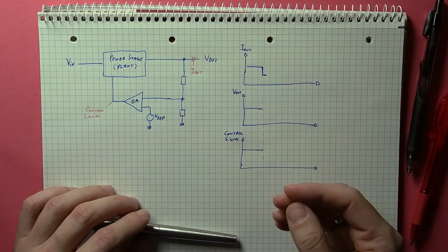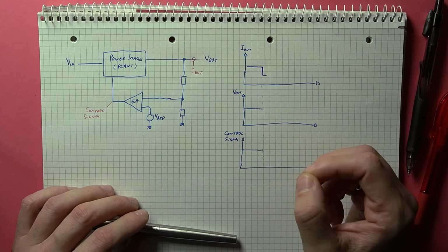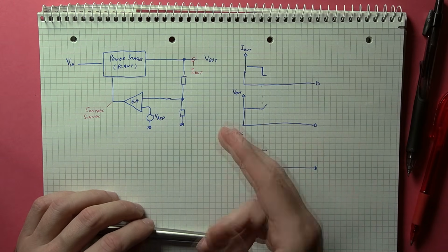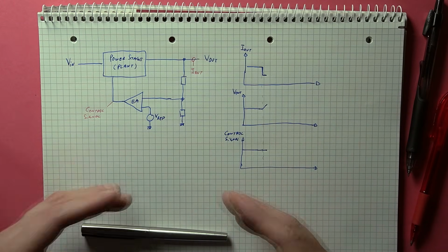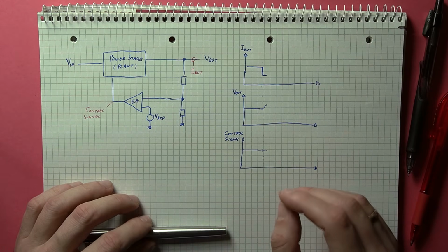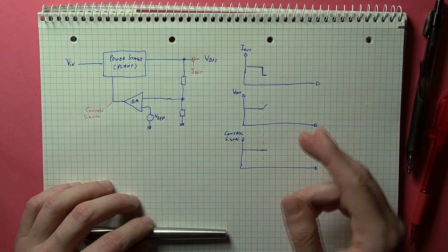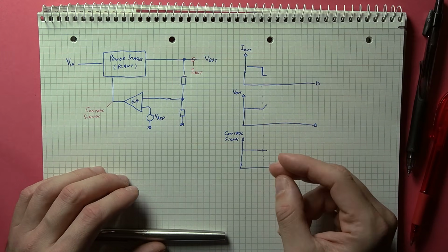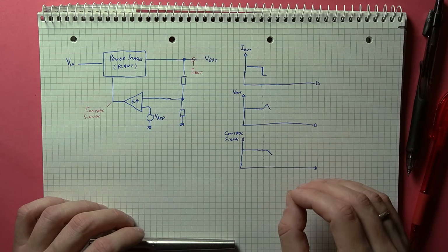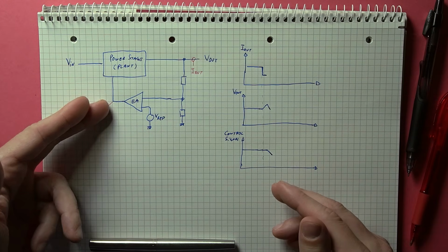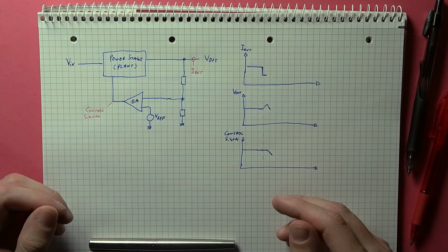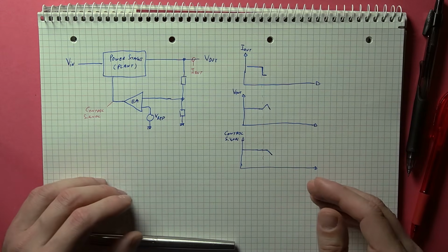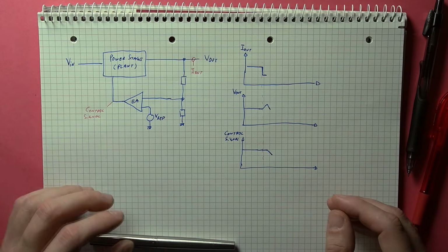Now, for whatever reason, the output load suddenly changes, so it decreases. Because the information does not pass instantaneously through the circuit, it takes a while for the power supply to react. So in the very first moment, the power stage is letting the same energy pass through, so the output voltage increases. Only after a short period of time, the error amplifier reacts and tells the power stage to reduce the output. And from here, it takes again a given amount of time for the power stage to, well, react.